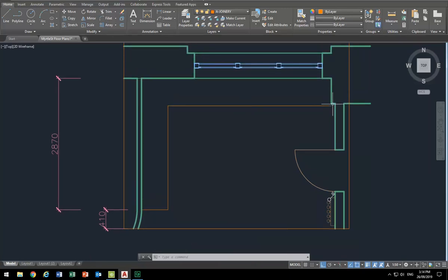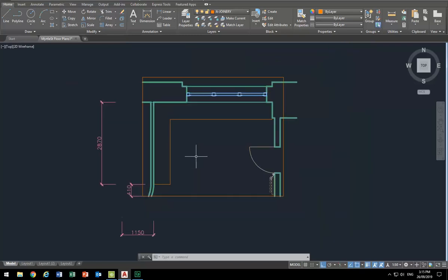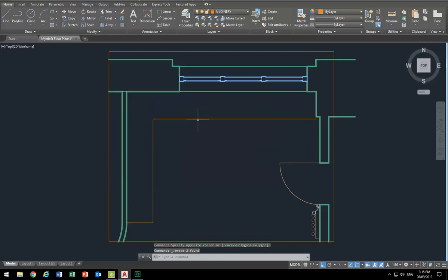And so normally, if you're going to give a set of joinery drawings to the cabinet makers, you would then do another drawing after this. You copy just the units out of this plan and have a floor plan that just shows the cabinets, and even take the stoves and the other things off, and then you can give them assembly drawings to show where it goes against the walls, and then you show your splashbacks and everything there. But we're just doing 1 to 20 plan of the kitchen, so it's fine here to keep those walls. So that's a good starting point. I'll just get rid of those dimensions, and we'll do a little bit of setup for the detail.